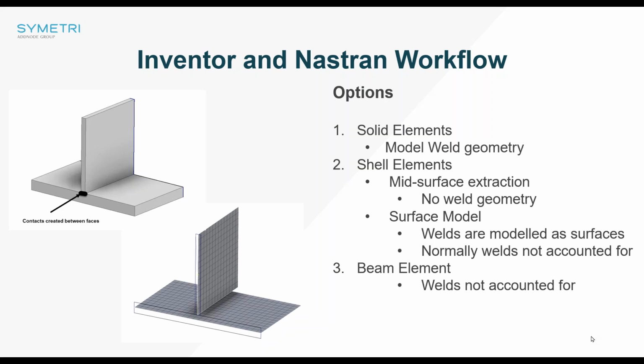So typically, I've seen many customers using fabrications or thin structures and still meshing them using solids. If that's the case, then we will get contacts between two solid plates. The contact is going to be highlighted by a black line. We're not going to get contacts on the edges. It's primarily going to be automatically created between the plates. Whereas in real life, when we're doing welded structures, the contact remains free and we have contacts on either side of the plates, or maybe even one side.